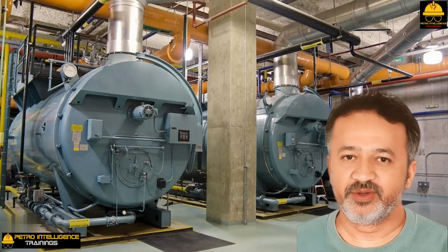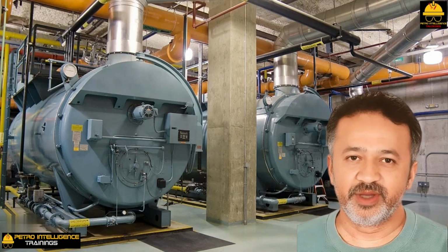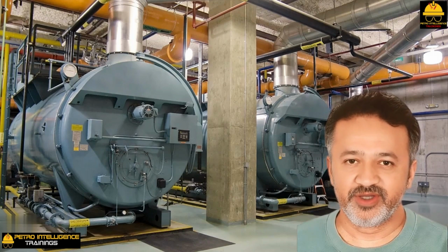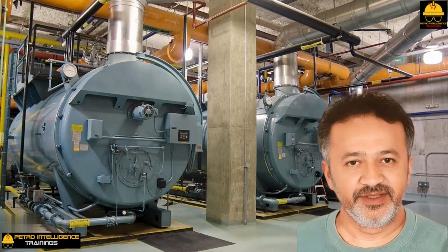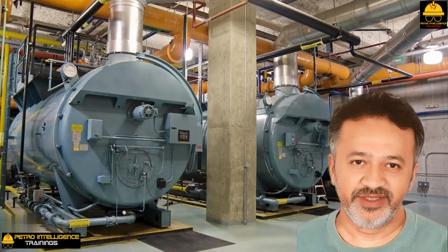Effective air preheat on boiler capacity. One of the first questions that many people ask is, our utility plant operators have observed that when they preheat their boiler combustion air from 20 degrees Celsius to 220 degrees Celsius, steam production drops by around 3 or 4%. They are forced to reduce the firing rate because the radiant section of the boiler starts to overheat.